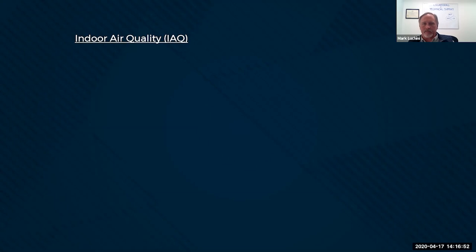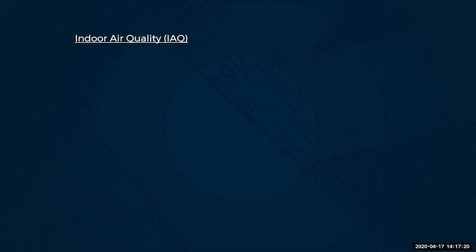But it will come into factor when you're plugging in numbers for infiltration and ventilation. Right, that's infiltration. So if you know you're going to have a good AVB and you're pretty confident that it's going to get installed right, then you can keep your infiltration numbers low in your calculations. So it's a leap of faith a little bit.